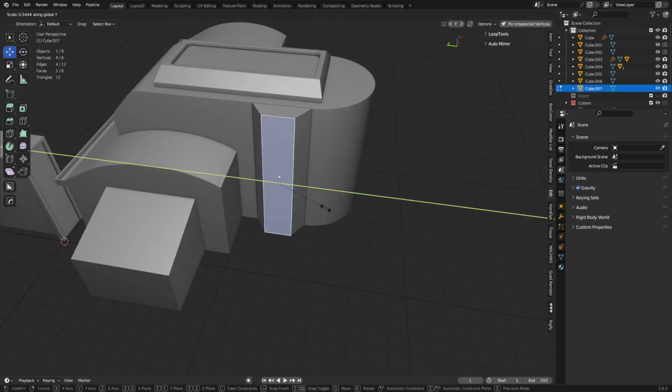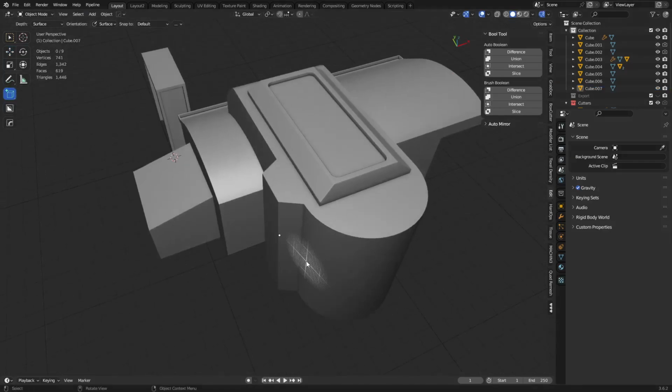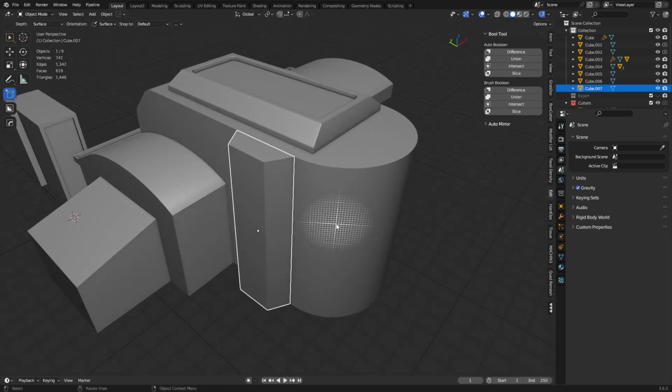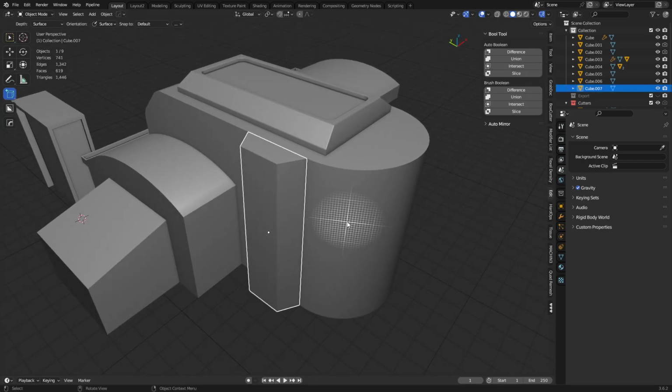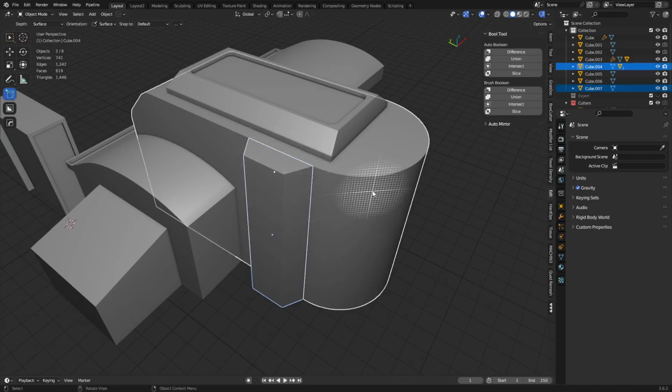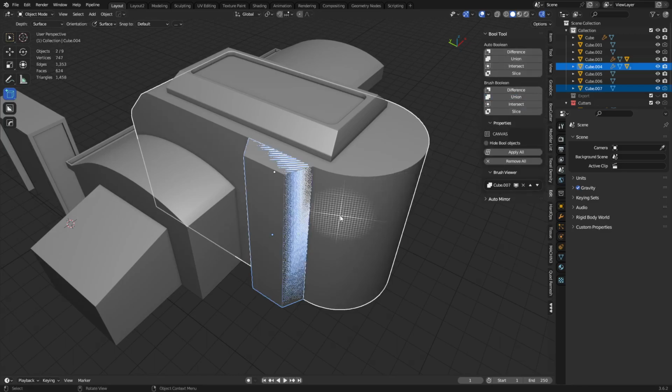Manually adjust these later. A fun thing about Bool Tools is that it uses the exact solver when you do a Boolean, whereas the default settings for Hard Ops Box Cutter use fast. Fast allows for more cuts, but exact allows you to do things that you normally wouldn't be able to do. So for something like this to be joined to this, usually you'd have to have them intersect just right. But when you use the exact solver, you do a brush Boolean union, for example.